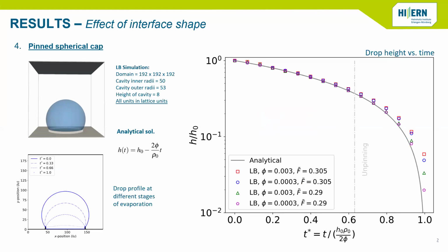So this is the equilibrium drop profile. The drop profile is essentially pinned on the outer edge of this cavity. And then you evaporate it like this. So this is my best effort to pin the droplet. However, in lattice Boltzmann, for those of you who know, even if you try to pin the droplet, the contact line would still move very slowly. It is still moving. So eventually you'll see it still gets here, and after a while it goes down in the channel, right?